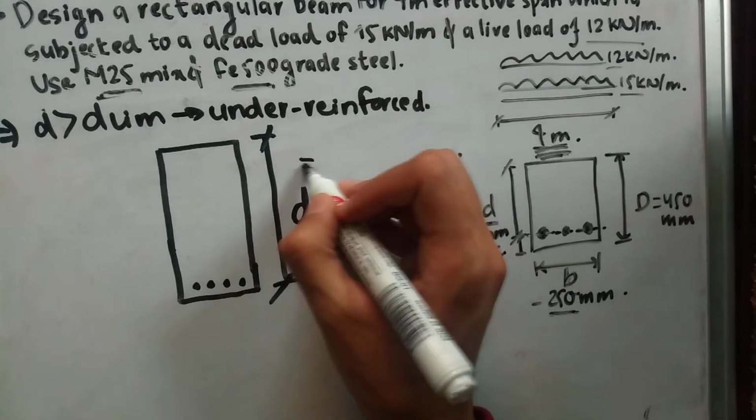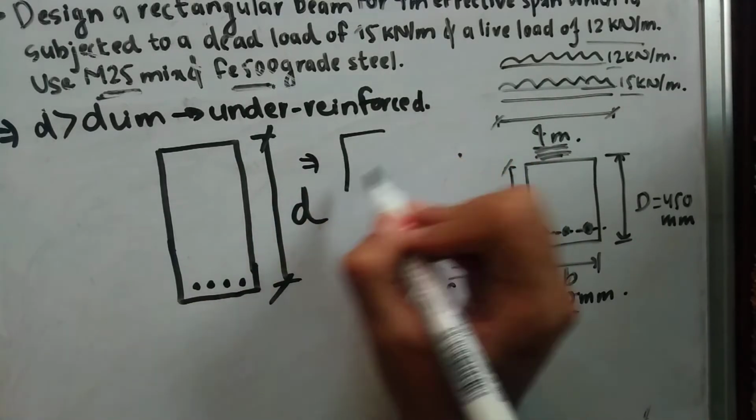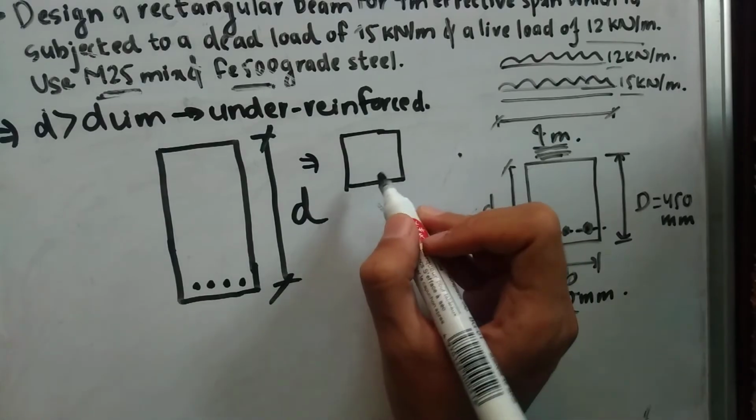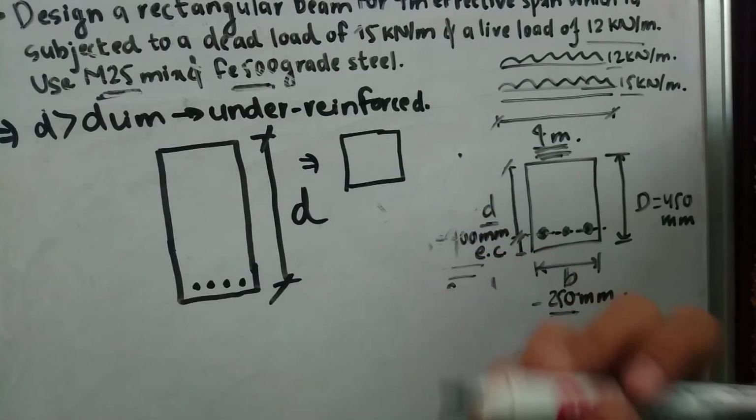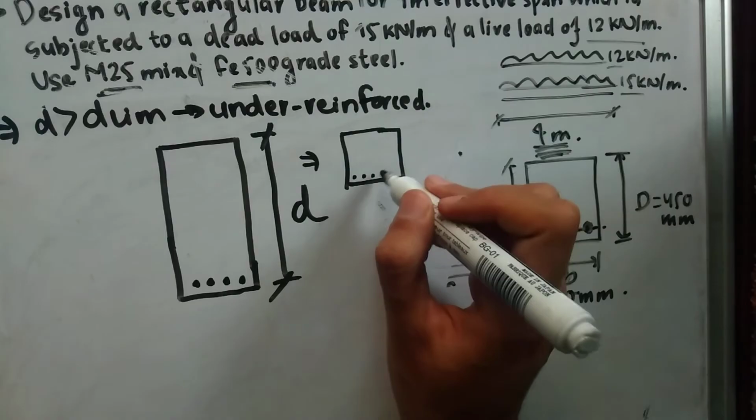Now in the other condition, if I limit the depth and keep a small depth, then in order to take the load, we need to give a greater amount of reinforcement.